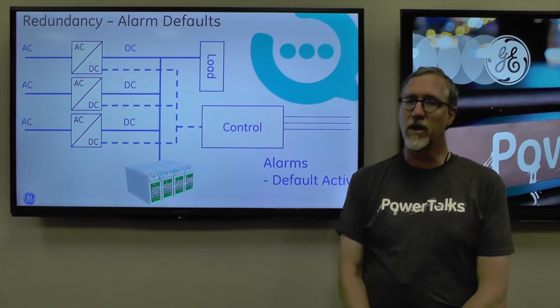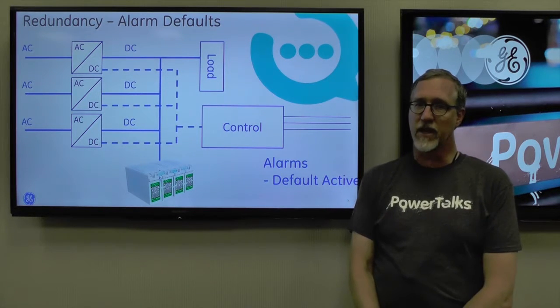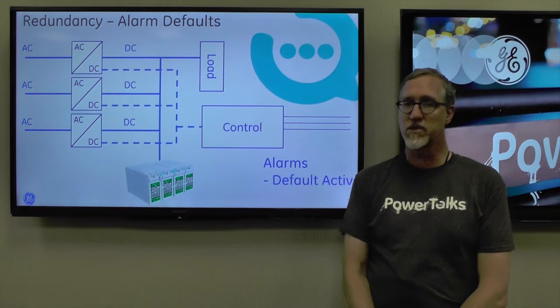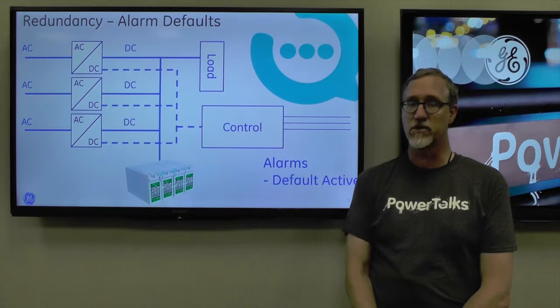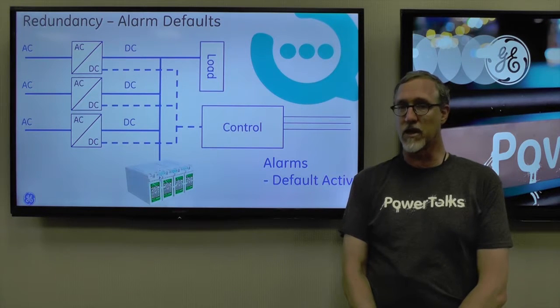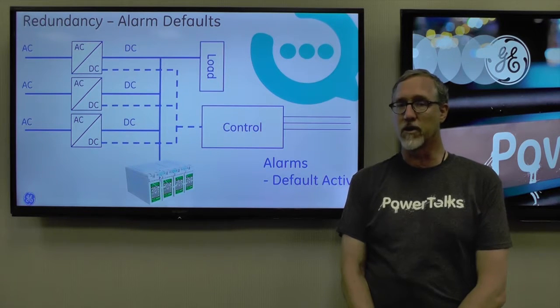Alarms can be sent two ways. The most common and reliable is the alarm contact closure. Alarms can also be sent via internet communications. Contact closures can be open or closed, but the best systems will use a normally closed contact, which opens under alarm conditions.